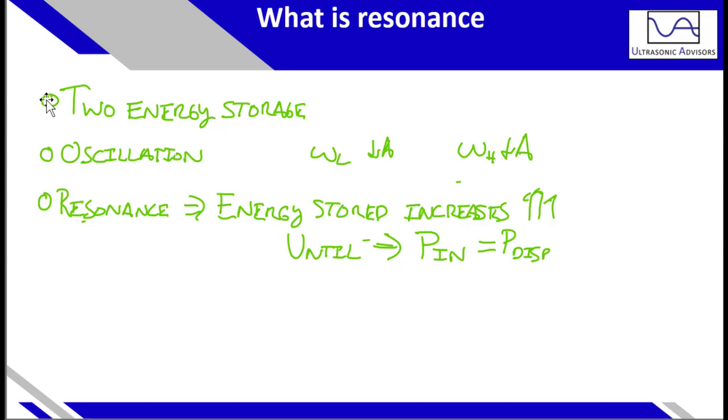So a person pushing at a certain force is going to reach a certain point where the losses in the system are going to equal the energy input. Because as you're increasing in speed, you're also increasing in losses per cycle. And assuming that you're putting energy in at a certain power, that trend may not be linear, because when the person is going faster, you're able to put in more energy for the same force.